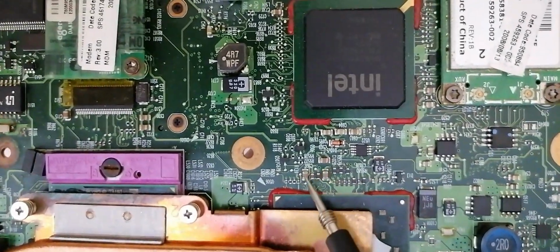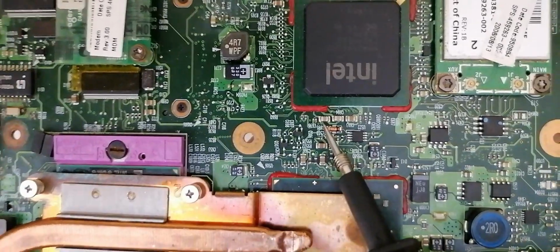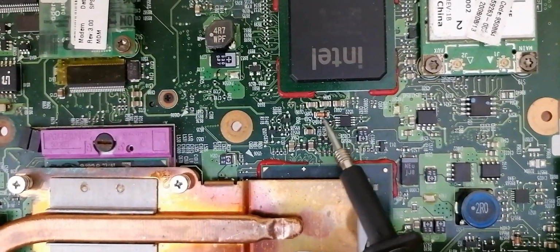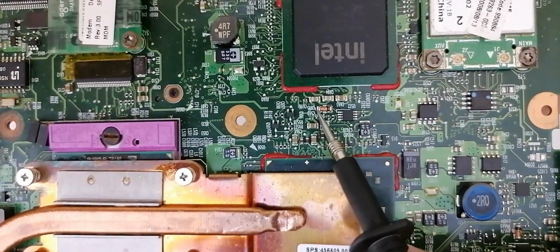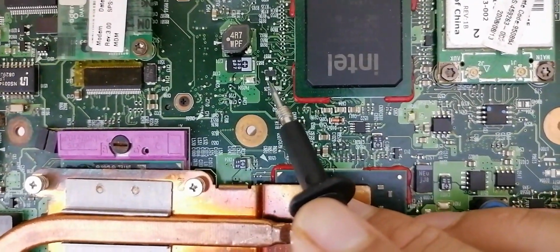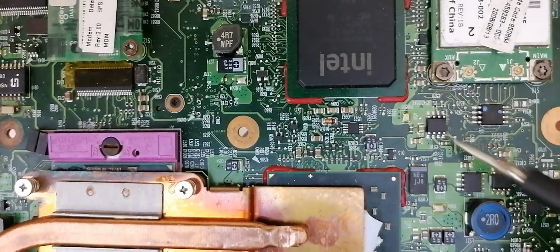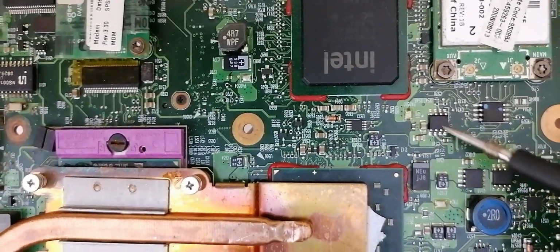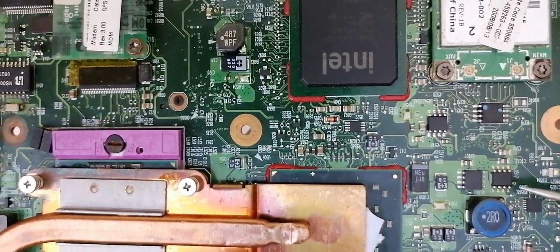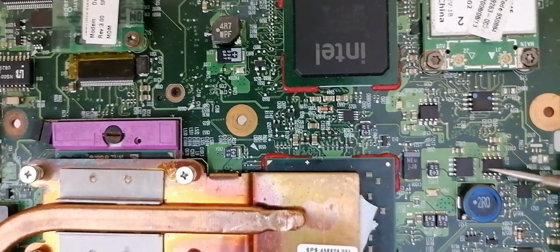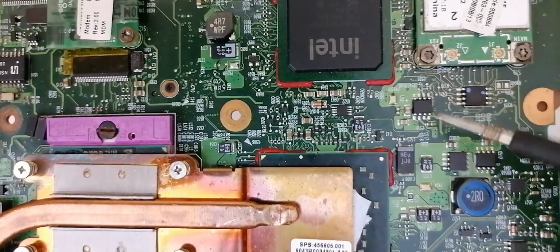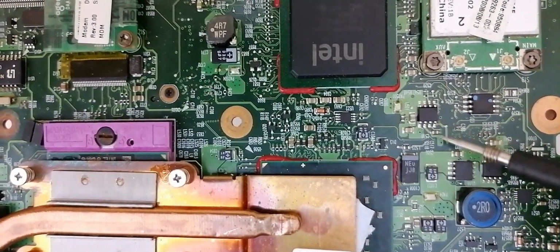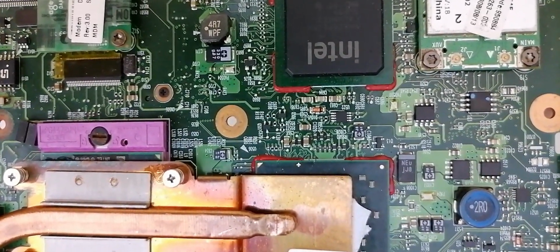This is basically a ceramic capacitor. And here we have a Zener diode. As you can see, this is a Zener diode. Here we have the cathode and here we have the anode. This is basically a transistor. Here we have MOSFETs. This is an 8-pin MOSFET. So in the motherboard you can find this kind of MOSFET, 8-pin MOSFETs, where you find 4 pins for drain, 3 pins for source, and the 4th pin is for gate.